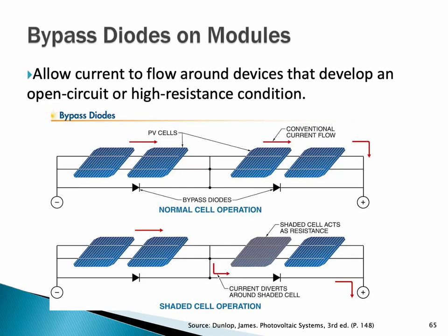I wanted to show you this. I don't think we've seen this before. This is the blocking diode concept. Here's one cell group. Here's another cell group. And then here are the blocking diodes on a possible detour route. When things are operating normally, current is flowing from negative to positive through these wires right here, these pickups.